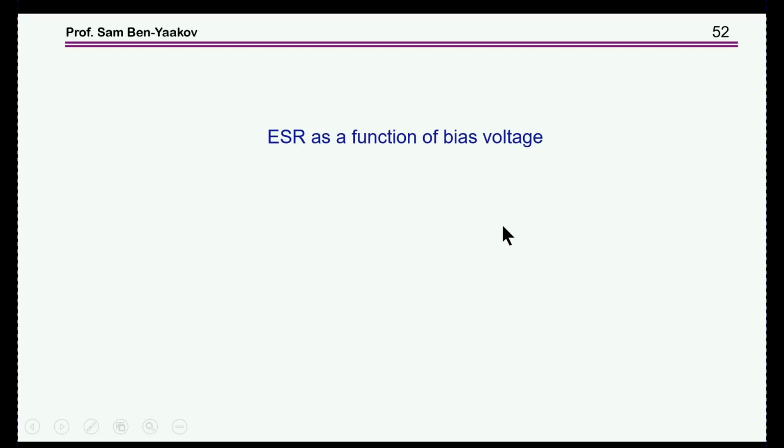And it turns out that this is incorrect. Okay, so we are getting the wrong power dissipation of the capacitor if we use the ESR from the data sheet for the 0 volt biasing while we are biasing the capacitor at a higher voltage.